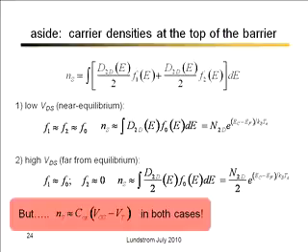But the thing that's really important to remember is that MOS electrostatics doesn't care that only half the states can be occupied. If you put a charge on the gate, it has to balance in the channel. The same amount of charge has to be accommodated now in only plus velocity states. So things are a little bit different inside the channel. Under low VDS, it's very near equilibrium. Half the electrons have positive velocity, half have negative, but here it's very far.